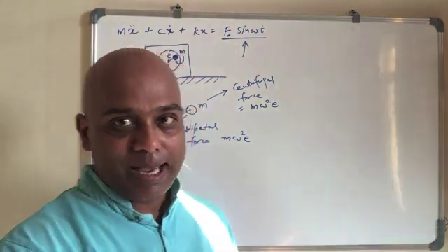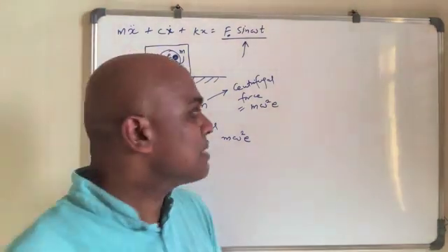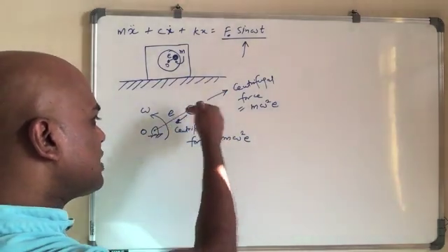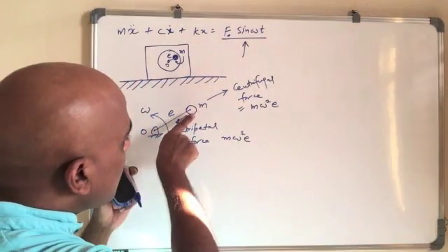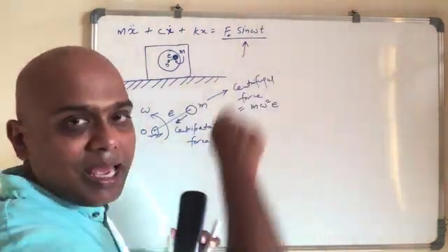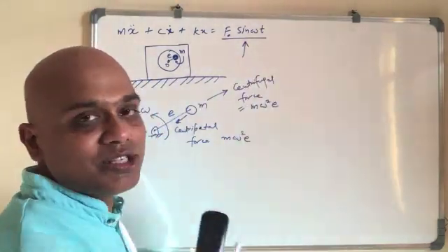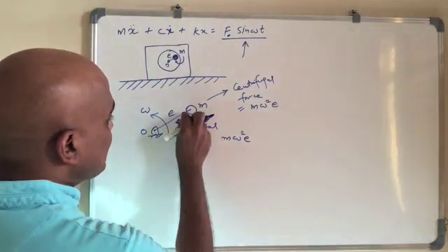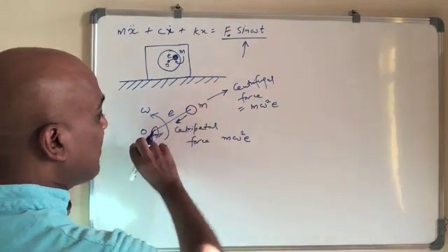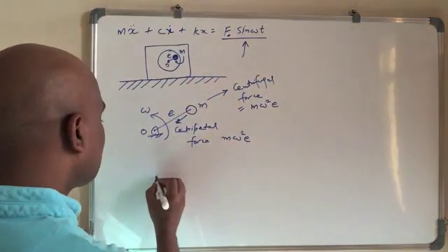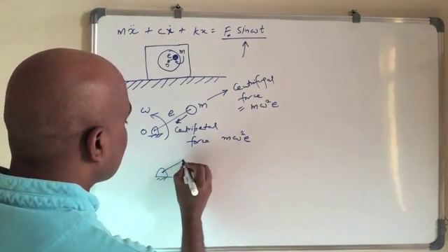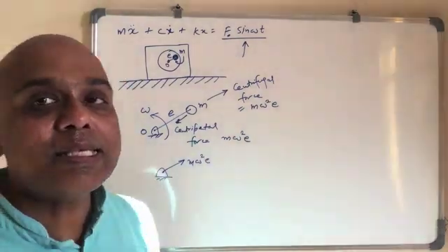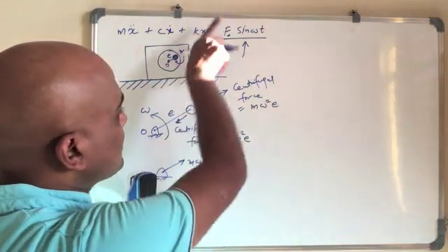You will feel a force as if somebody is pulling you behind. Similarly here, since when you are rotating this one, acceleration is towards the center, hence there is a pull outside actually. So this is what the centrifugal force is. That means if this is a string, then there will be a pull in that direction. And what will be the pull? The pull in this direction will be equal to m omega square r, and this is the force which will be applied this way.